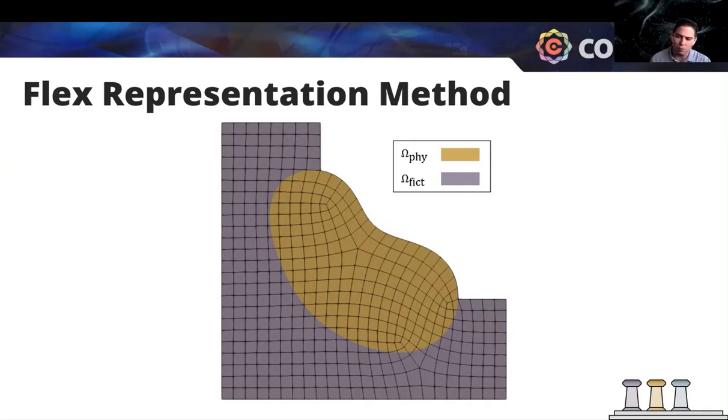However, U-splines allow us to build novel envelope domains that can partially fit to the physical domain, as we can see here at the top right of the jelly bean. And that can increase the accuracy per degree of freedom in those regions. So if those are critical areas for your analysis or for the results that you're trying to process, you may want to have partial body fitting in those regions.